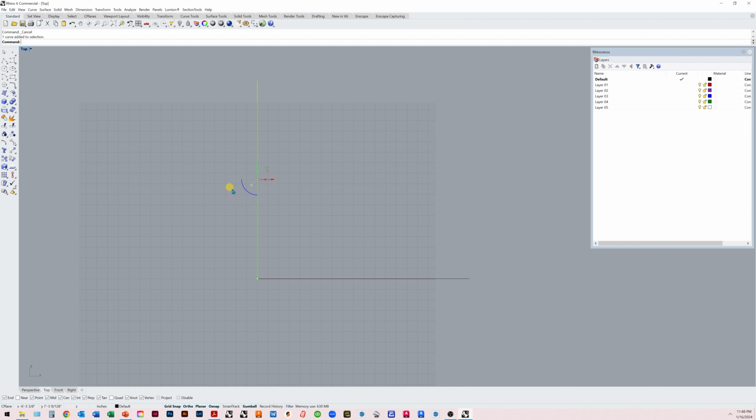So the gumball allows you to move things around in space. If I click on this arrow, it will just drag this line directly along one axis. If I want to go up and down, I can drag it along the other axis. And I'll show you how this is useful in a minute. If I want that line to go back where I wanted it in the first place, I just undo what I was doing and hit Control Z. That's another command that will be your friend, Control Z. All right, now it's back at the origin.